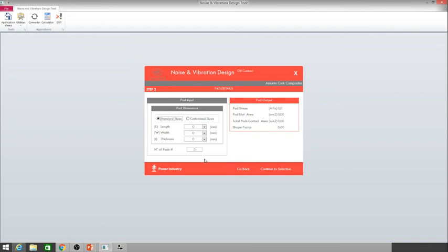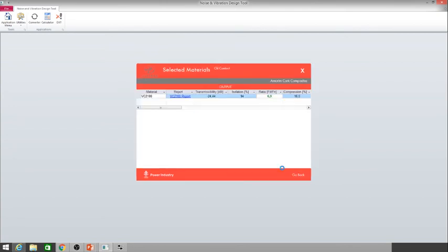In this case, we could use a customized solution, 500 by 150, which is the width of the supports, by 40 millimeters. And this case is a little bit more complex. I will not take too much time. I will just input 14, and you can see why I've selected 14 on the possible solution. So the pad stress is within the limit, shape factor within the limit, and you have the report.